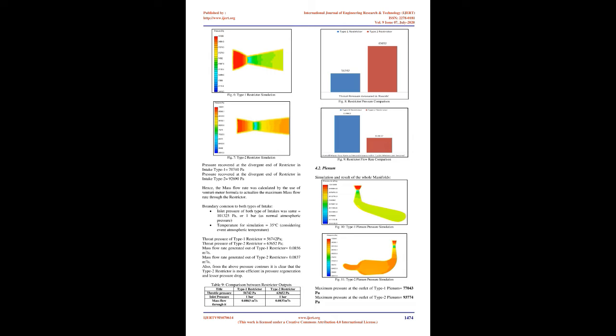Table 7, Comparison between runners. Type. Runner length: 307 mm, 381.77 mm. Runner diameter: 46 mm, 46 mm. Methodology: David Vizard's rule, acoustic wave tuning and reflective wave theory.